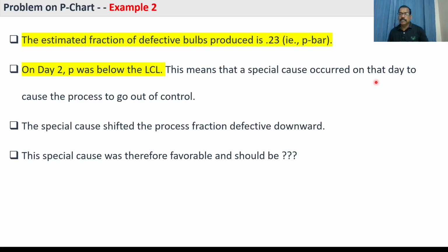Since I said, from the control charts, either attribute or variable charts, you should understand and infer something from the chart: whether it is out of control or within control, or going one-sided, either on the upper control side or the lower control side, or evenly distributed, or both, like 10 points with 5 above and 5 below. You have to analyze that. Then only are you completely understanding the process. So all the data will become available in your chart.